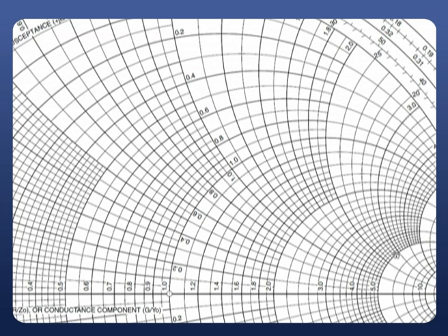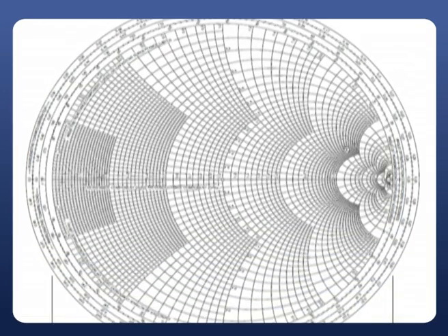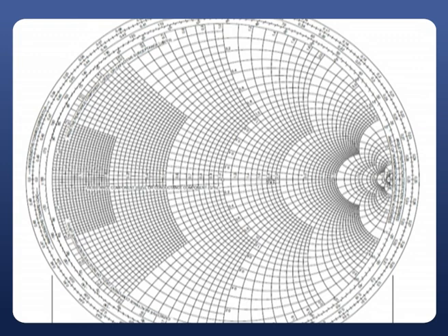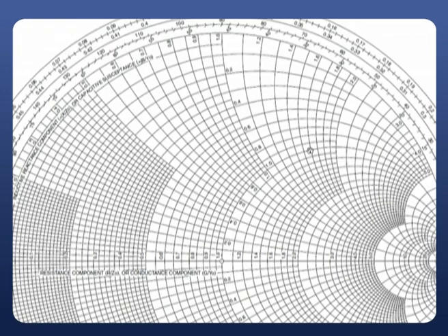This x equals 3 circle is meant for normalized reactance, and it is also positive, as I said. While we are drawing these circles, the upper part of the horizontal line, the horizontal line that we are supposed to consider, which is meant for gamma r, is always meant for positive reactance. Just observe the positive reactance.